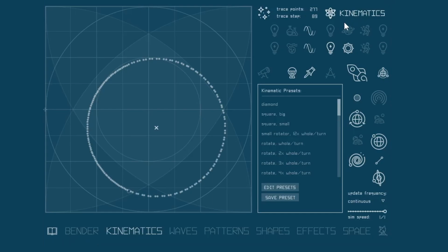Rotation speed is defined in degrees per half node. Don't ask why half. So set it to 180 degrees and it will take whole node to make a full turn. At 90 degrees it will take 2 whole nodes and so on.